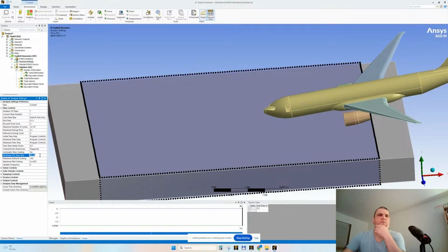So we're imposing a CFL time step of -6. We had a time increment of 3 at the power -6. Let's make it 1 at the power -5. Let's see if it works. All right.